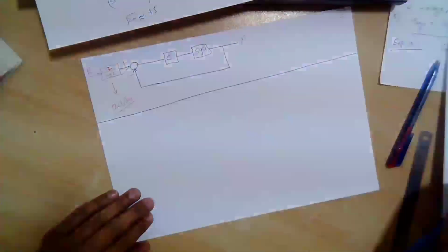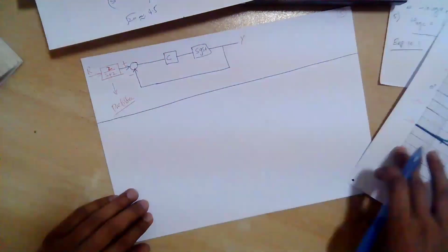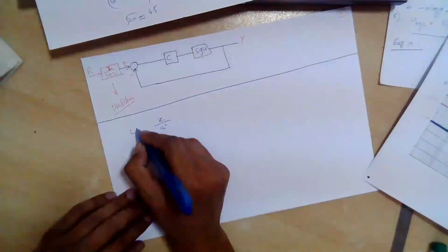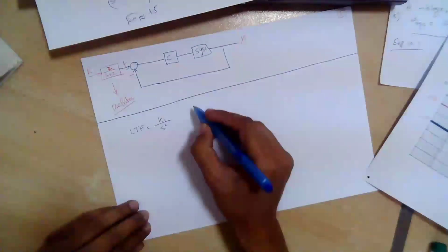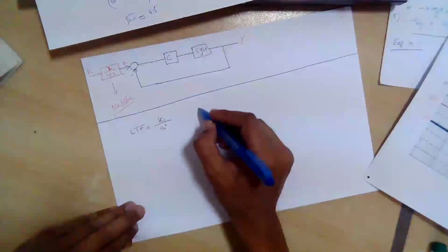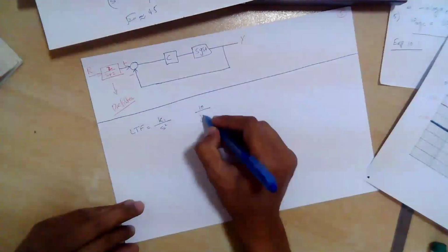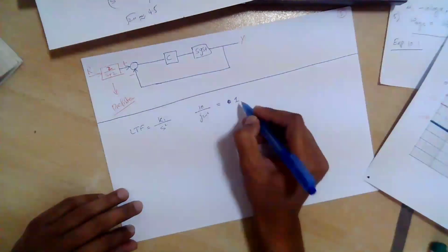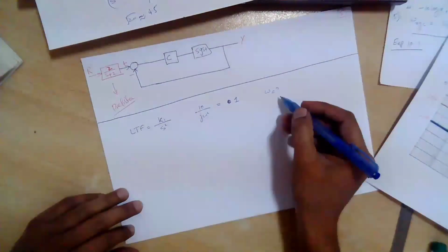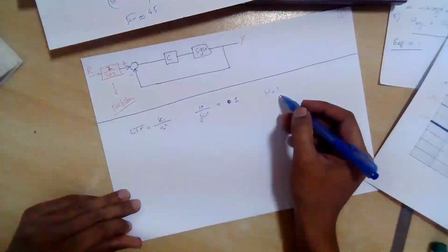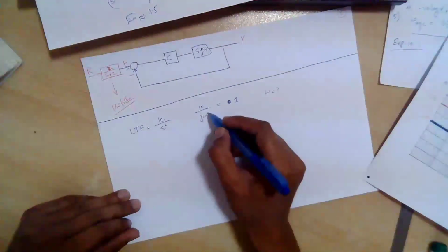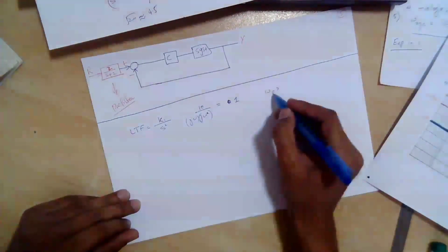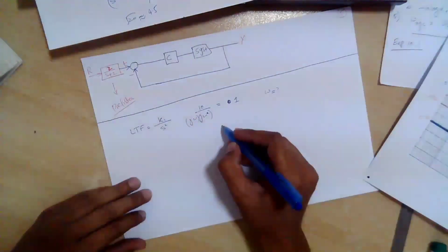Just like we're plotting this loop transfer function Bode over here, it's a very simple system. So we can directly write k1 over s square. This is loop transfer function, right? So we can calculate the magnitude and phase of this system if k1 is 10 over j omega square, and if I put it equal to 1, I can calculate omega easily because it's a very simple system. Omega and j omega, two poles, right? So I can calculate omega corresponding to magnitude 1, and I can calculate the phase over here.